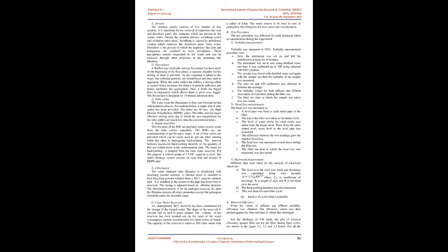The size of sand required for a particular purpose will vary depending on the purpose. To increase the surface area of sand grains in the sand depth of the bed, the finer the suspended particles to be cleaned, the smaller the sand size should be. Due to the greater effective size and the lesser uniformity coefficient than that of SSF, the void space in the filter media is increased, which results in a higher rate of filtration.